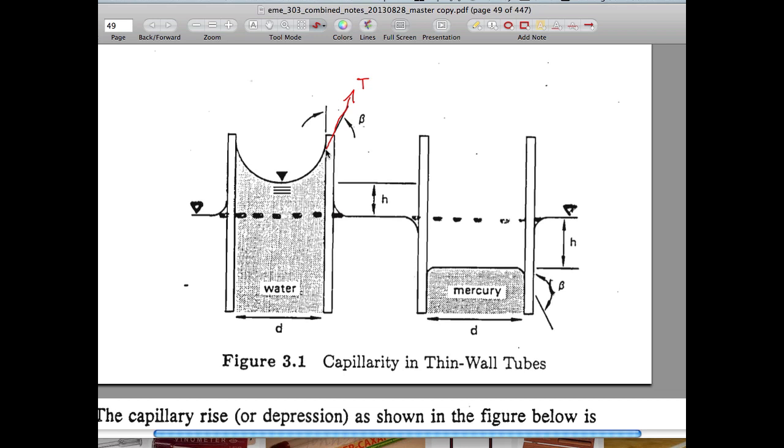And so one way to analyze this is to be able to understand the magnitude of the effect and define the magnitude of the interfacial tension that allows this to happen. And so in basically characterizing this, the features of it are that if it is hydrophilic, then the rise in the tube will be above the datum. This is the datum of the water that's pushed into, and the portions of this curvature will be above this line here.